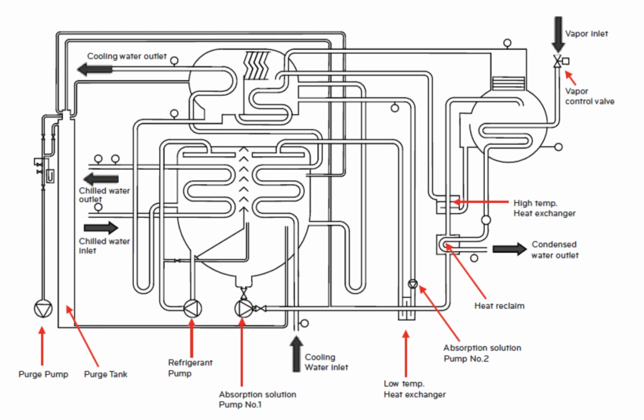Condensed refrigerant moves to the condenser, then returns to the evaporator, and the remaining refrigerant vapor which was not condensed in the low-temperature regenerator will be condensed by cooling water in the condenser. Refrigerant in the condenser returns to the evaporator and will be circulated as above.